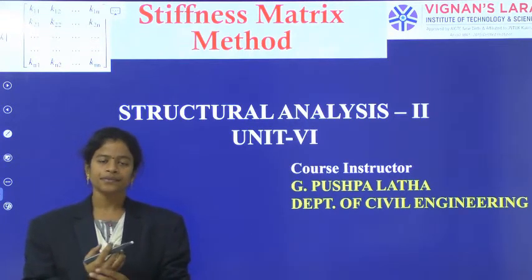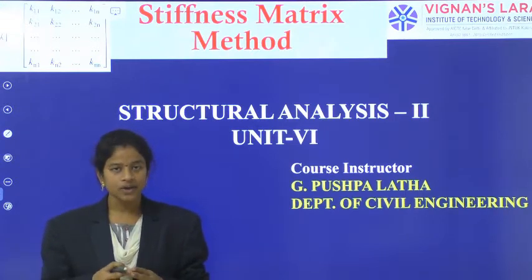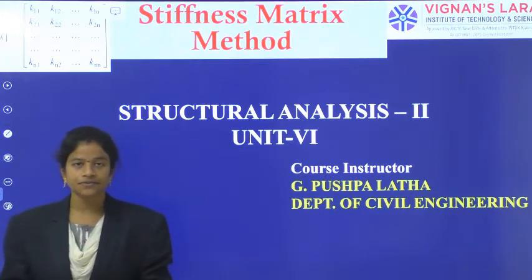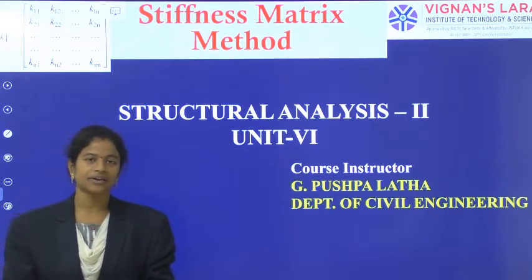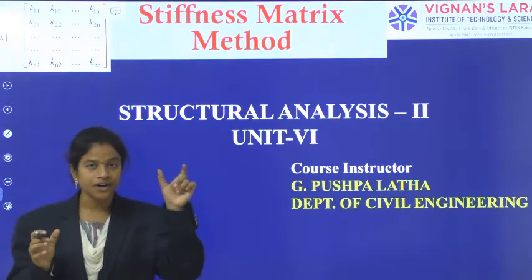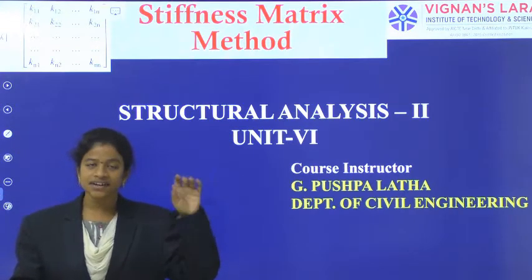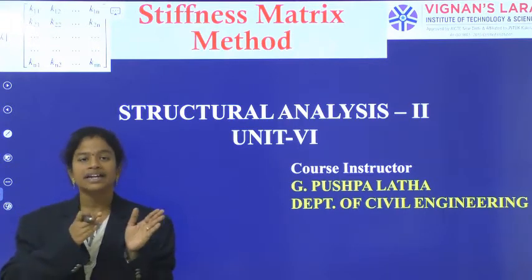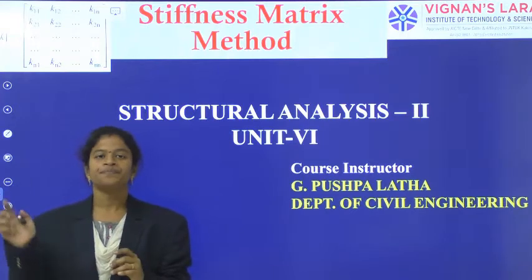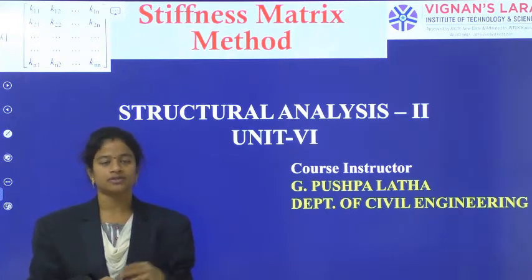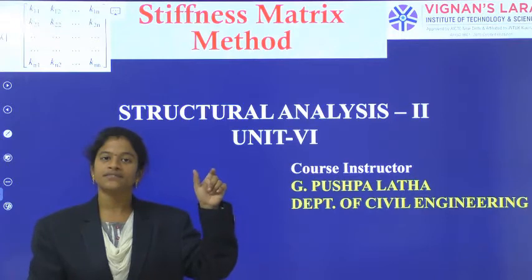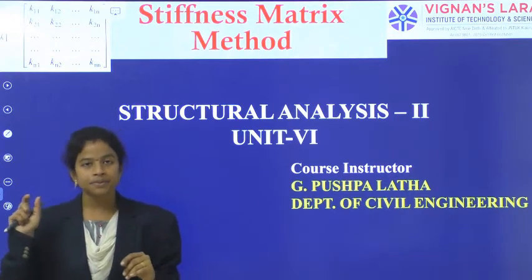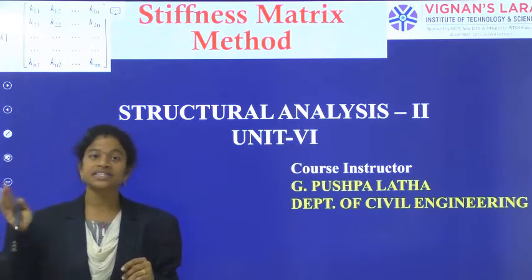Now in the stiffness matrix method, as we have already said, in flexibility the forces are the unknowns, whereas in the stiffness matrix method, displacements are the main unknowns. Generally, the word force may involve moments as well as forces, and displacements may involve displacements as well as rotations.